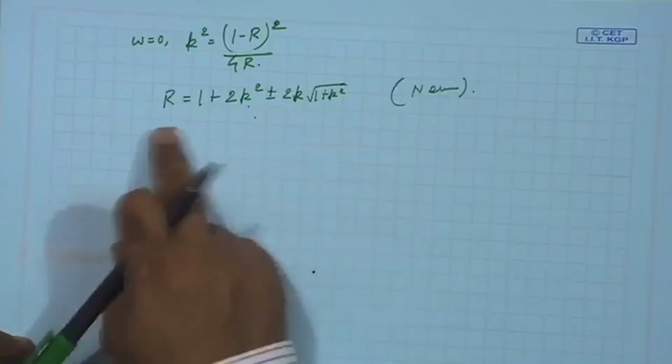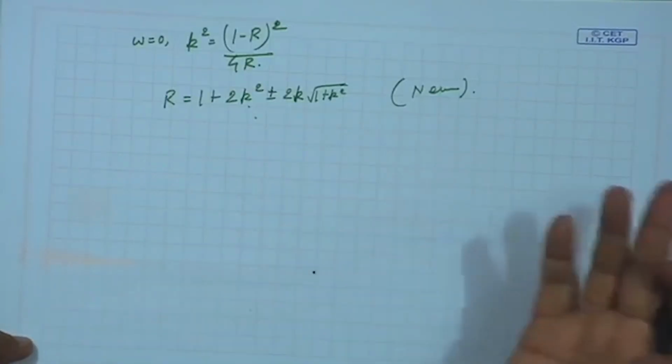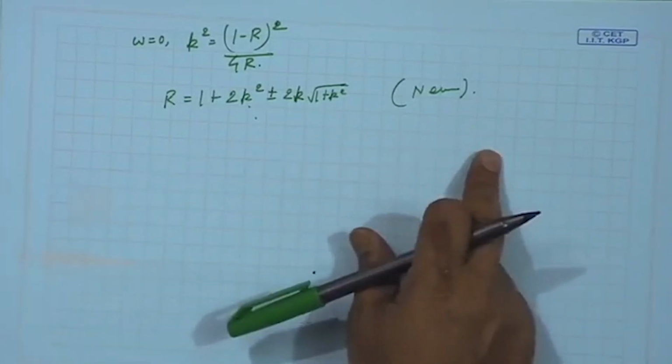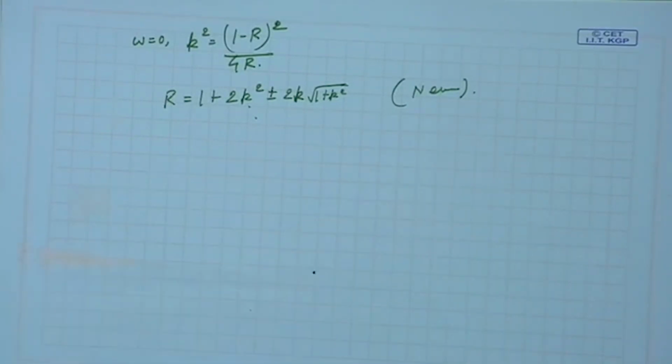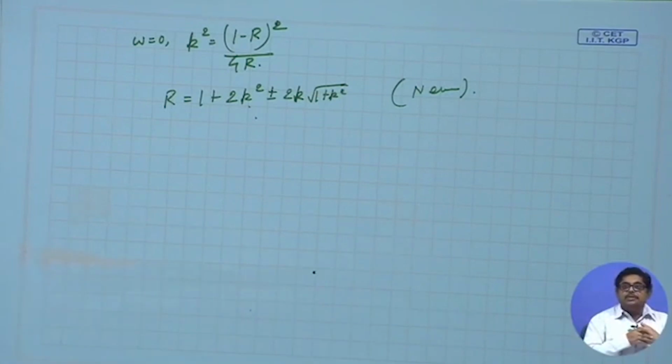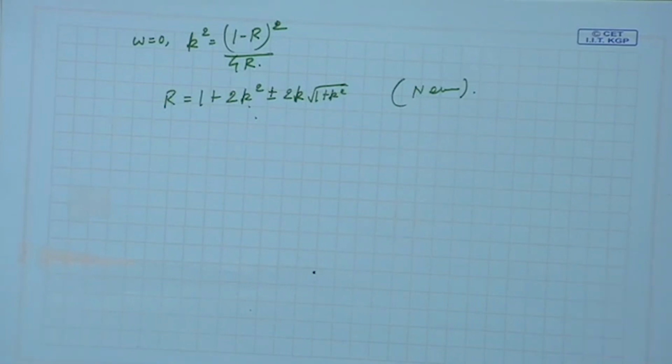Suppose you are having n even, you see this problem comes in n even, but if n is odd, then this is not there, r is equal to 1, that we have already seen. So, you can also do that, because for odd n, r is always 1 for Chebyshev. So, you try to make n odd there. So, you can design for various ripple values these tabulations are available.